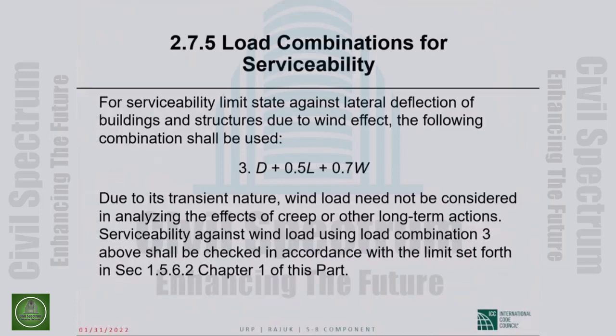So for serviceability limit state against lateral deflection of buildings and structures due to wind effect, there is no serviceability under earthquake that I'm aware of. We are concerned about strength in seismic design, not serviceability. It is understood that there will be damage.